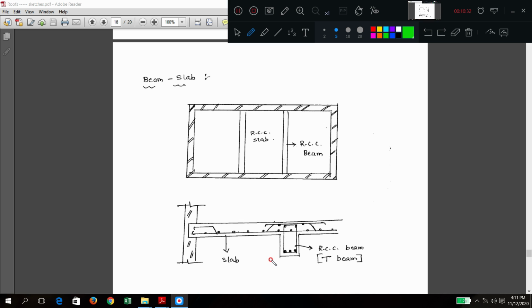We have seen the previous diagram, how that depth was there to have a concrete beam. I have shown in the shuttering, first slides. Try to remember that one. This is the typical sectional diagram showing reinforcement for beam slab. You have formwork like this, or the base is like this. You have steel, main steel, cranked steel. These dots are nothing but distribution steel or secondary steel or main steel itself, because if it is two-way, then both way steel are called main steel only.